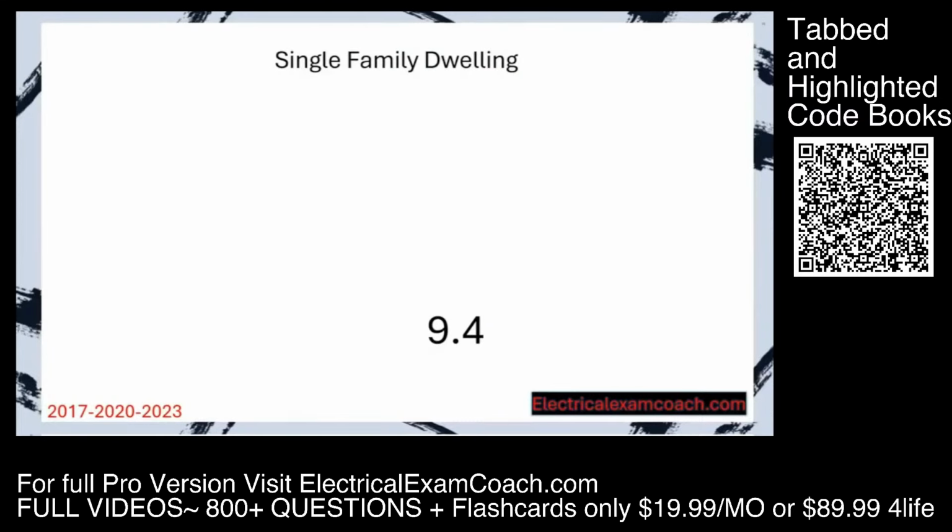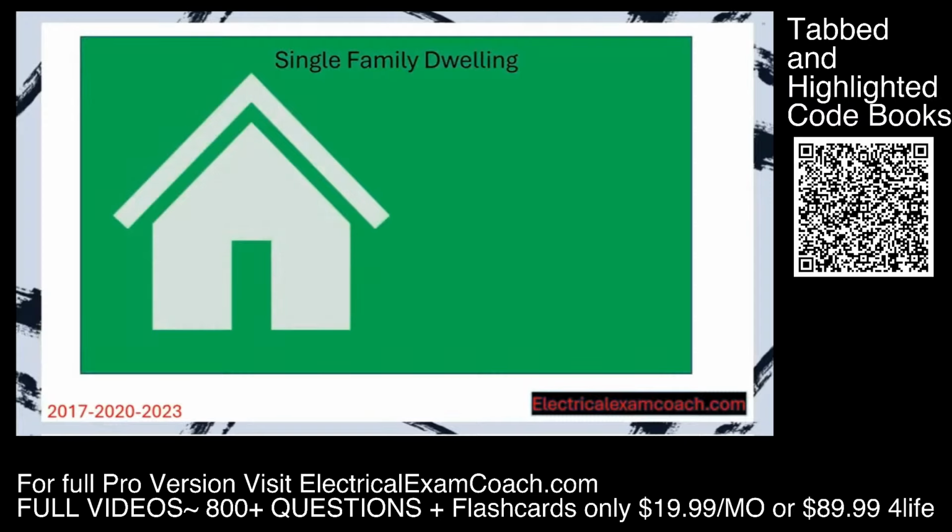Now let's find out when this rule does and does not apply. Let's imagine that we have a single family dwelling. We have the meter socket outside, we have the riser, and we have a back-to-back panel, kind of an old school setup. We have the wire going up the riser and the wire going inside. Technically, this is all service wire all the way to that main breaker, and the 83% rule does apply here, as long as it's between 1 and 400 amps.